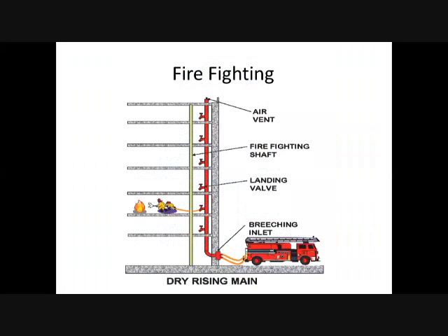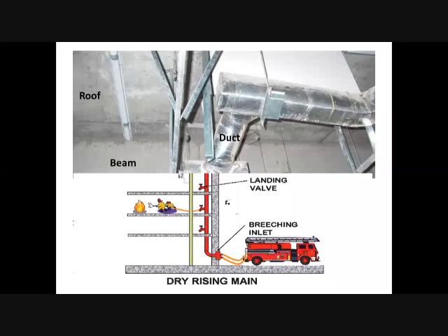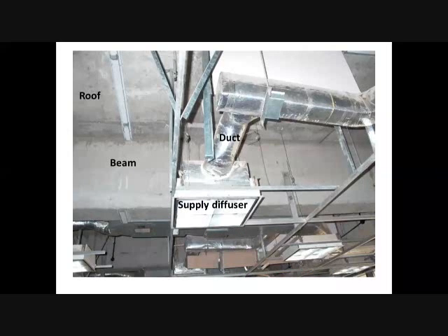Another important system, yes. Sorry, but approximately what is the height of the false ceiling? Is it always 30 or 40 centimeters, or 20 centimeters? No, of course, it's much more. It's usually 60 to 100 centimeters. It depends on the size of this duct. If this duct is big, then we need to have a larger void. But 60 is minimal.